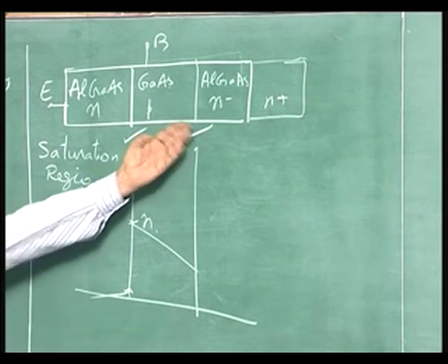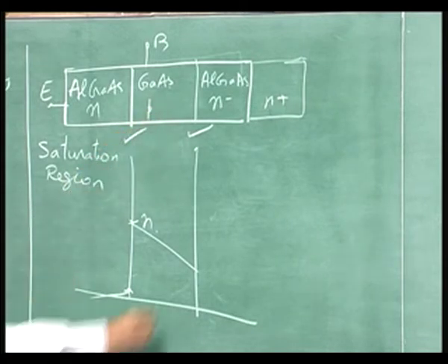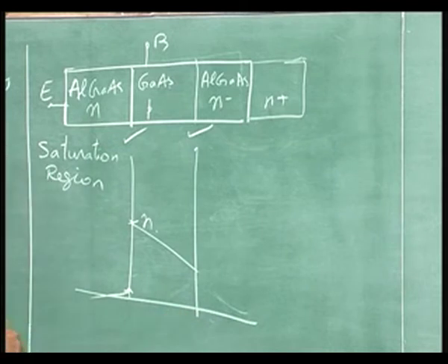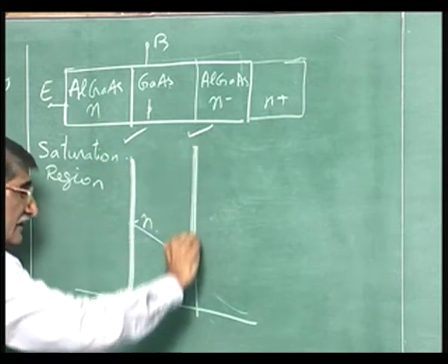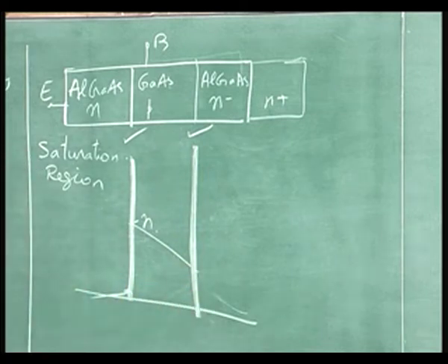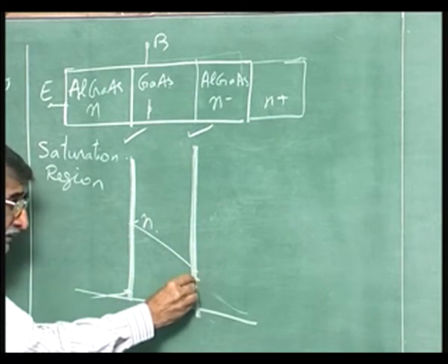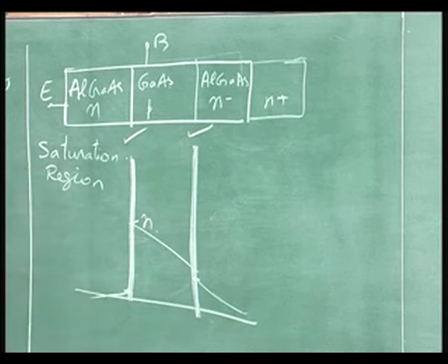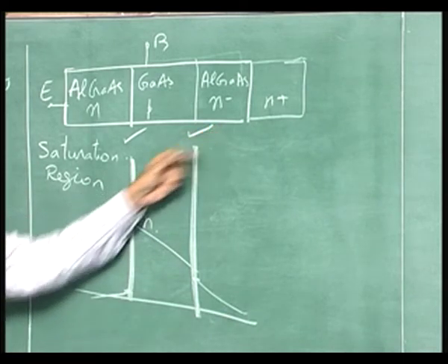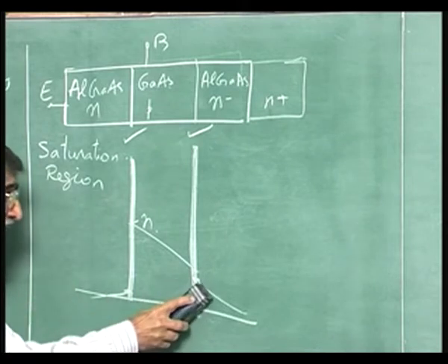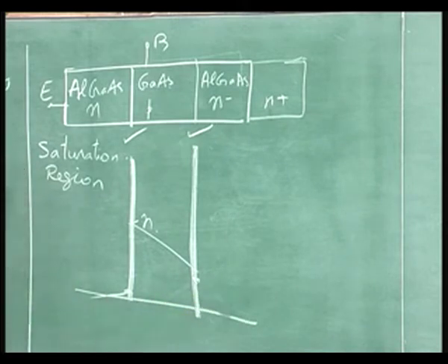If this were the same gallium arsenide, you would have got the hole concentration reaching like this. Of course, I just draw a small region there to signify the transition region. You would have got high concentration hole injection like that if it is a narrower band gap material. If it is a wide band gap material, what happens here? Same thing.